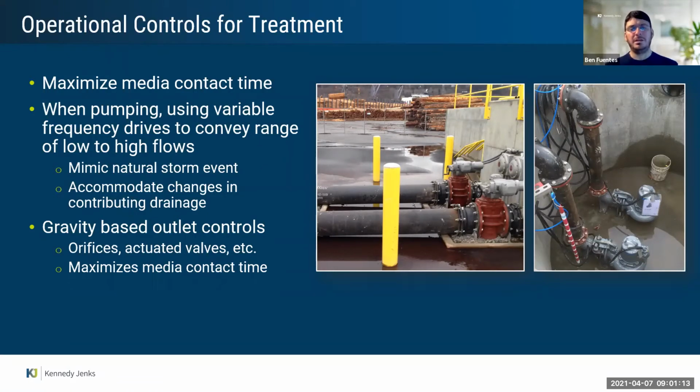And then there's a lot that can be done with outlet controls. Ideally you can do quite a bit with just gravity-based outlet controls using orifices. If you did go a more mechanical route with actuated valves that are based on water level sensors, quite a bit of options there. And ultimately the goal is that you're slowing the water down and you're maximizing that media contact time, getting that water fully distributed across the entire media bed, just to improve that treatment contact.